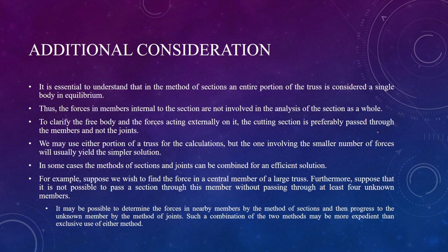An alternative notation preferred by some is that you can assign a common positive or negative to all the forces. You can assume the forces, if positive, to be in tension, and when you solve these calculations, the algebraic relations will distinguish the true positives from the false positives, and you can identify those false positives as compression.